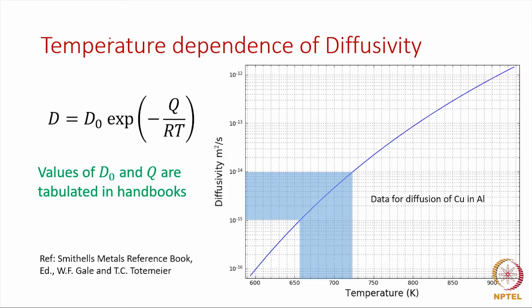And now that's significant, which means that when we measure the temperature in the experiments and say that plus or minus 10 Kelvin is the accuracy, then it actually implies that the diffusivity values are changing by about 100%, that is a factor of 2, and that's quite significant when we plug in the numbers later on. So we have to be very careful with respect to these estimates because of the sensitivity with respect to the temperature.